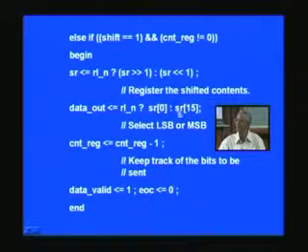That means this is a single bit as such. So I think this is clear to you. So that's what the comment says. Select either LSB or MSB, of course depending upon whether this RLN is 1 or 0. And having done this one, we should not forget to decrement the counter, because we started with 16 earlier at the reset time. Now that 16, when it has decremented, would be 15.